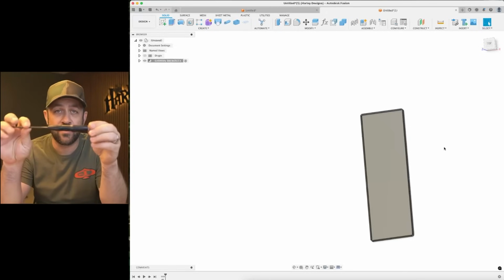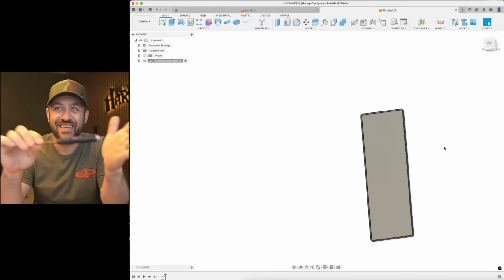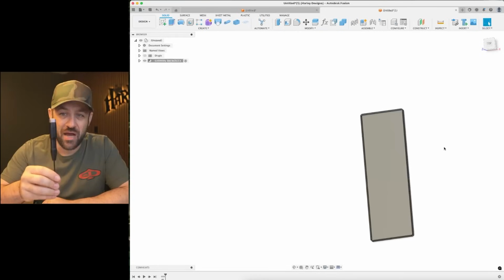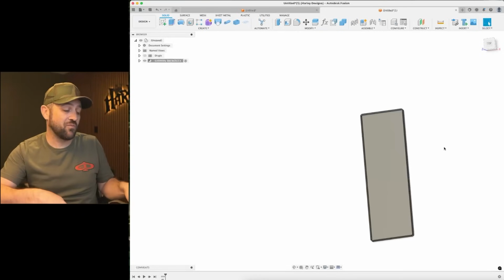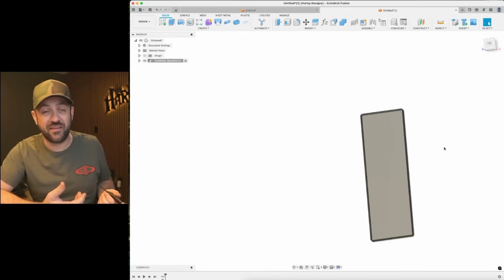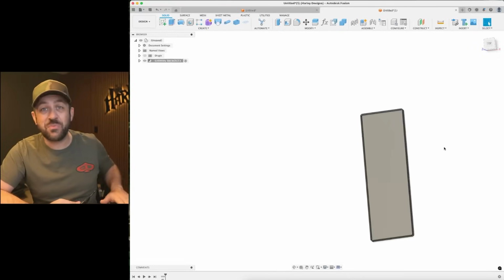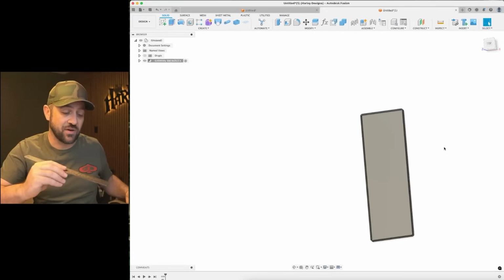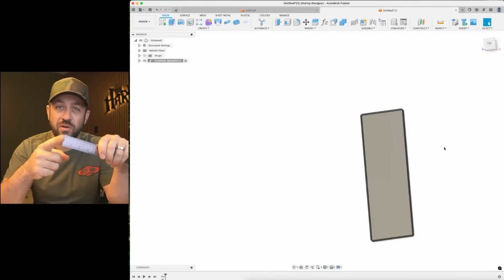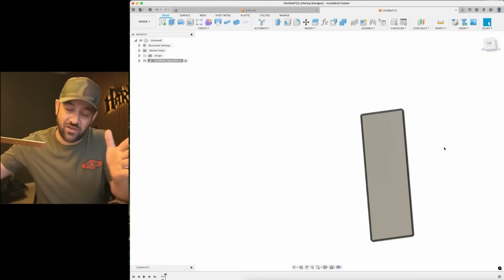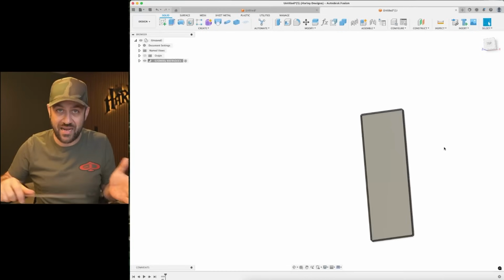This is the tool holder or the tool itself in question. So rather than actually super closely modeling this, I'm just going to take some very rough measurements for some things, especially when you want some tolerance in the design or significant tolerance even. A ruler is super handy. Buy yourself some metal rulers. A 12-inch and a 6-inch is great to have. Also nice to note to get one where the 0 mark is on the edge, so that there's not a buffer. Pay close attention to the photos when you're shopping so that you can put it right up against something and that is your actual dimension.